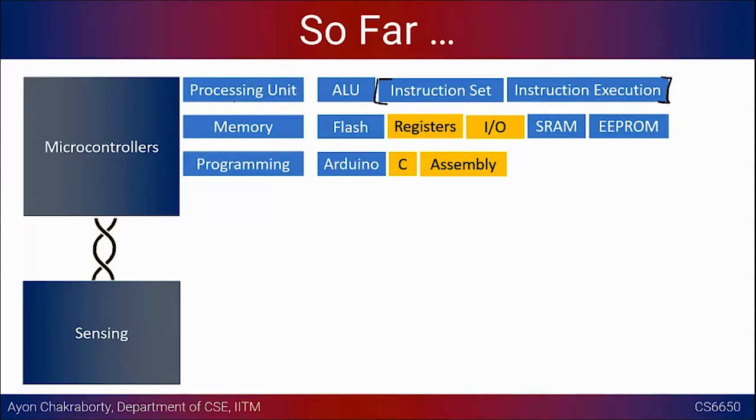And as I told you, I have given an example in the last class that you can program the microcontroller in the form of a sketch, the way we were doing using the setup and loop, if you are using the Arduino IDE. You can also write a complete C code if you are using Atmel Studio or any other IDE which is used to directly program the microcontroller. You can use pure C using the header files provided by the vendor.